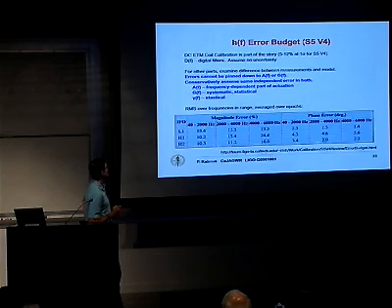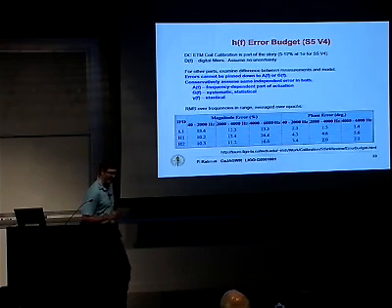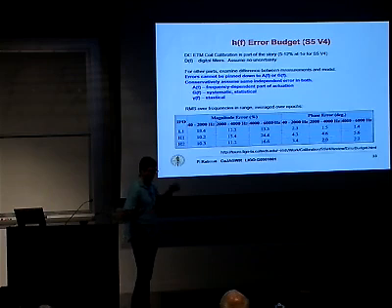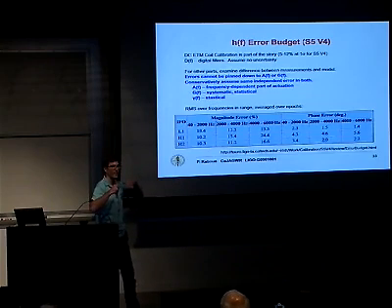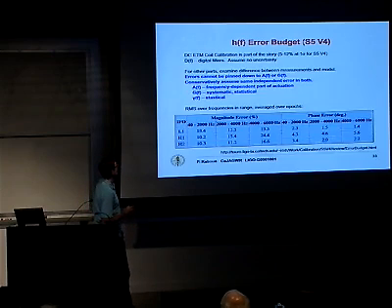This actuation function is dominated by the uncertainty in the DC calibration, but it has a relatively small frequency dependent part as well. You measure the open loop gain a lot of times, and every time you get something a little different, so there are statistical fluctuations in your measurement of the open loop gain. Then you compare the average of that to your model, and it doesn't always match completely well, so you have to take that into account.